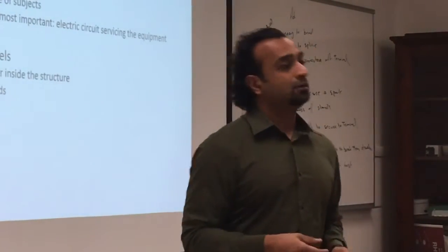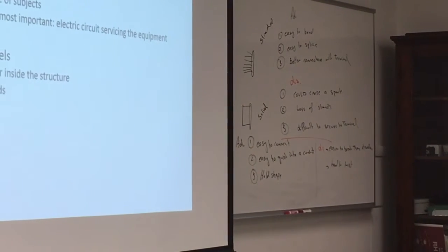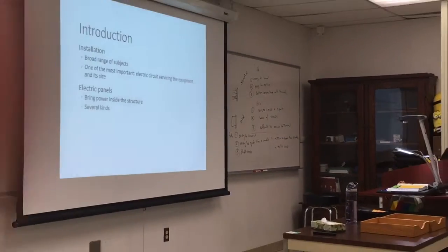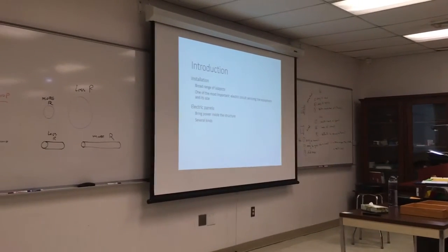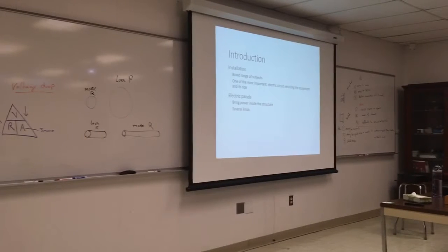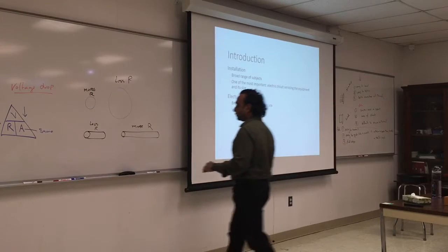Is it possible? Well, is it the code to connect stranded and solid together? No. People do it, but it's not the code, you're not supposed to, because again, you have different connections. One of the problems with connecting stranded and solid is you might connect only a few strands and not all of them. If they are uniform, it's easy to connect. So I'm going to put that here so you will remember.